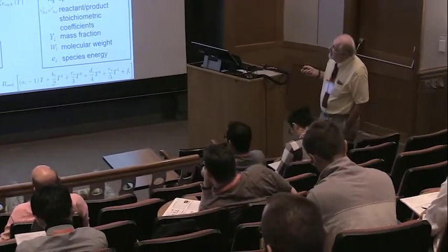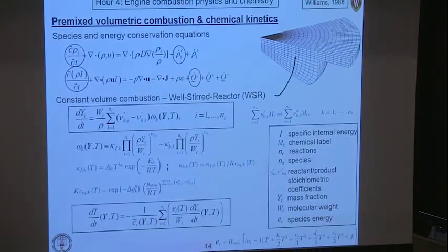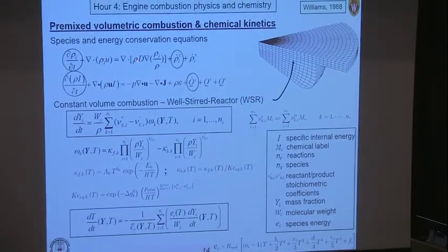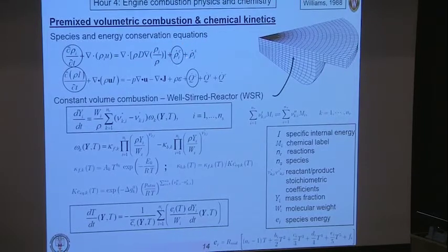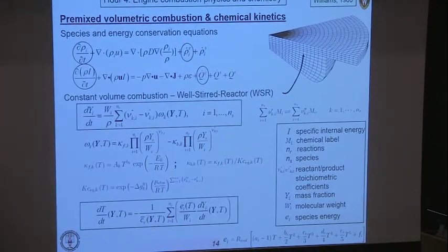So here we have, for species density, for species I, the rate of change with time. We have a convective term. We have a diffusion term. Then the circled one is the term due to combustion. Species I changes because of combustion. Later, we'll see that it also may change because of spray.